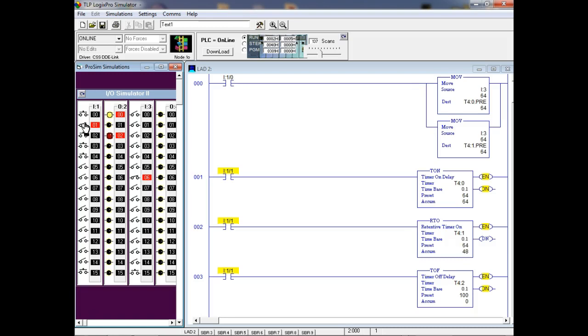So that means I'm gonna come up here and make the rung false. And what did the off delay timer do? Start a timer, right? And it's a non-retentive timer. So it means if I make it false, it goes back to what? 0. When I make it true, thank you, Jeff. It goes back to 0.